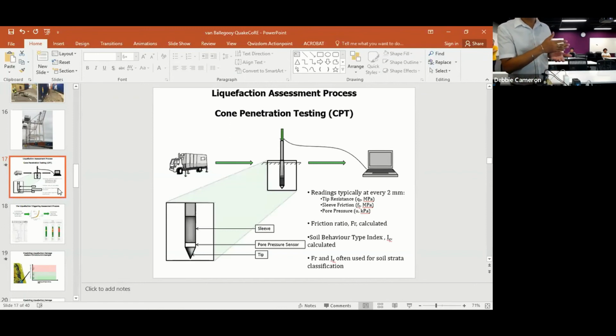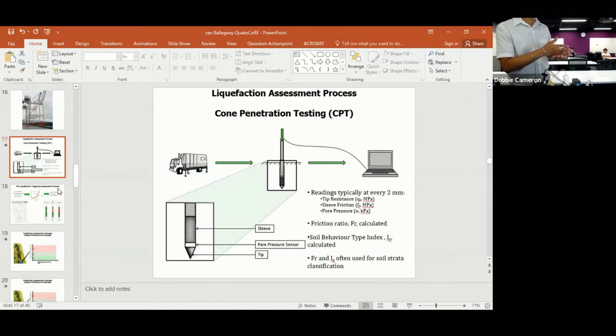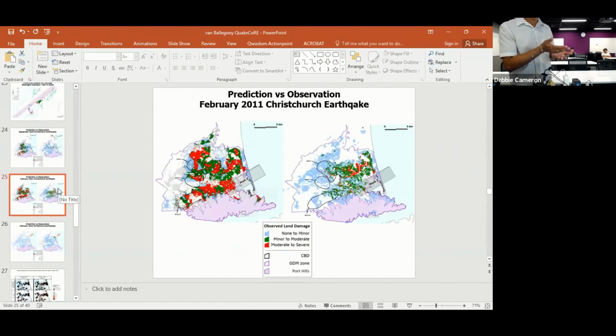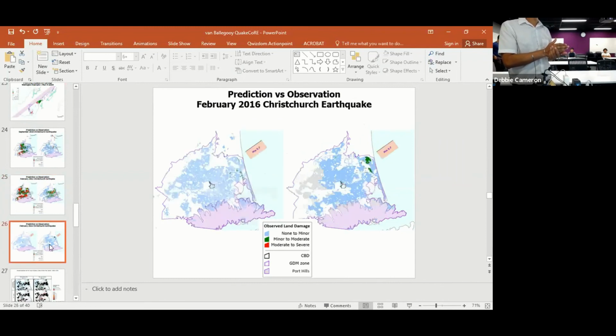It was interesting to see that for the February earthquake, there was an over-prediction where the shaking level was high. And if you compare that to the Valentine events, where the shaking level was low, there is an under-prediction. So there is a kind of contrary results to each other. Now, I was just wondering, what's the physical reason? Is it because of the uncertainty in the shear wave velocity profile? Is it because of the limitation of the method? Or is it because of both?